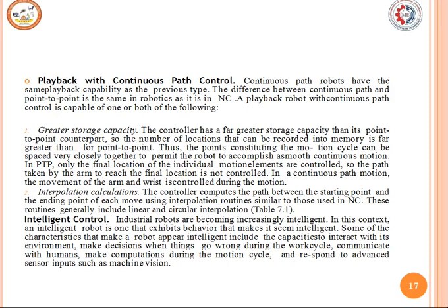Playback with continuous path. Here continuous path means where all curvatures are there, where all contours have to be generated, so it has to make a decision. It has to move in steps so that the required output is achieved. For that, interpolation calculation is required in the machine. Without interpolation calculation, you cannot get the exact path.